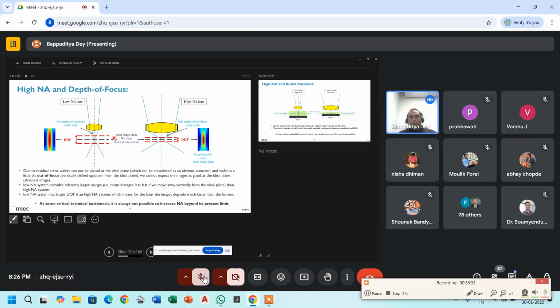For that plus minus 10%, basically it is allowable to place your wafer in this range. Ideally not, because there is also a mechanical problem: the stage is moving all the time, right? You have seen how it is printing, so you cannot stabilize the stage. It is inevitable that your wafer can be placed in any of the vicinity. So within this spec, if you place your wafer, it is expected that your spec is on target.